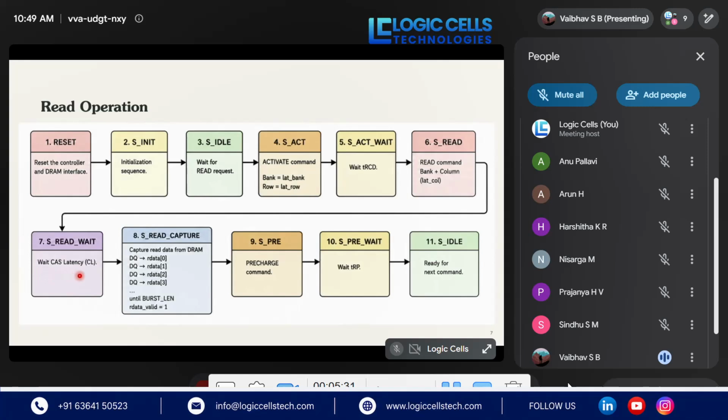Then CAS latency is executed, where read wait is the state. Next, the data is captured from the banks. Next, the precharge command is executed, where again the rows are closed for further operations. Here the precharge function ends. Next, the idle state is reached, which is ready for the next command.